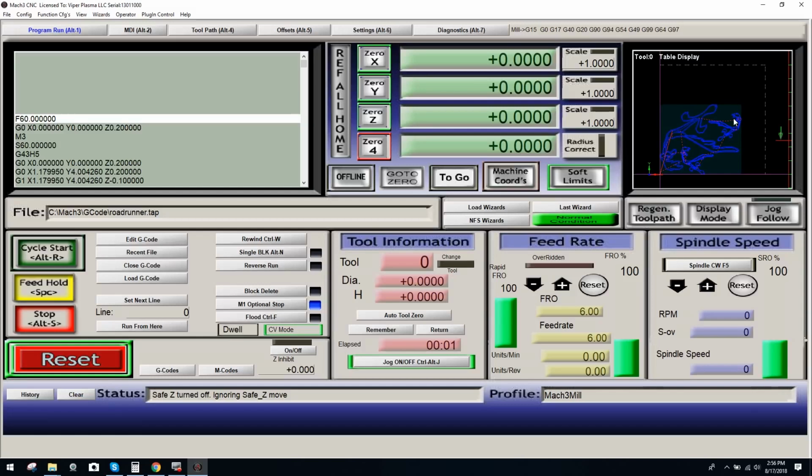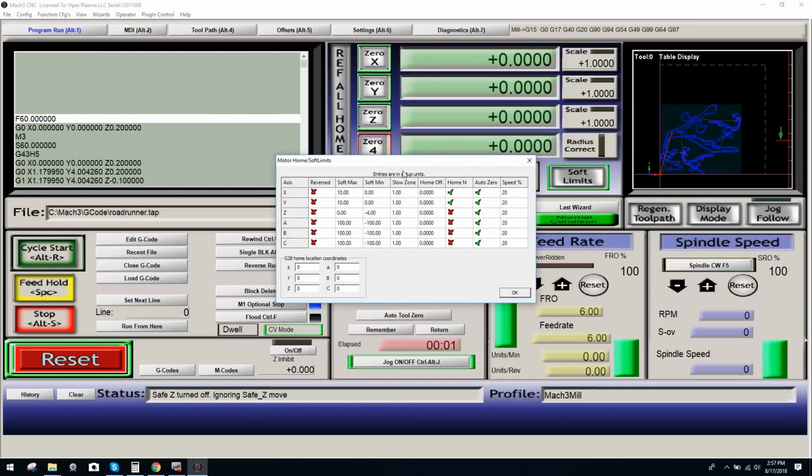Once again, if you're using your system as a true CNC, and even if you did have to change settings, because I get asked that question too, one of the things I want you guys to really do, especially now that you've got your pen and pad, is write down these settings as you're setting up your table. Record them. Take a screenshot. Hell, we've got technology. Use it. If you take these settings and copy them, resetting your table up takes minutes. It's really not a big issue to do, and it pays off overall.